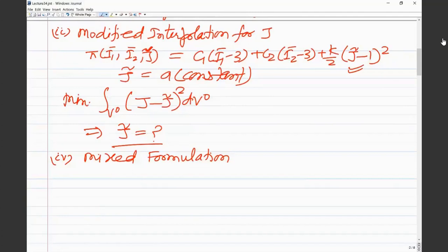In the determinant, it would be a cube of displacement gradients, as you see, because J is the determinant of F, which would be in terms of the cube of a particular deformation gradient or a product of 3 deformation gradient terms. So it would be like that.